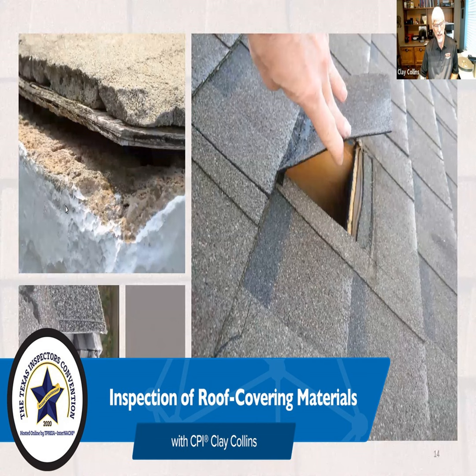Okay, over here, again, I must have been drinking on the left-hand side, but what you see in the upper right is just a lack of fasteners there. But if you look closely, you'll also see along that red line, which is at the end of the wood structural panel, there's not an 1/8 inch gap.